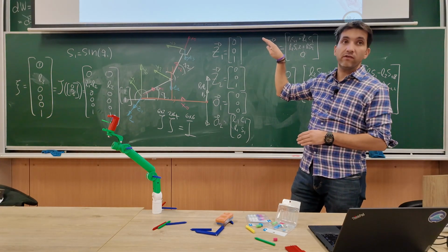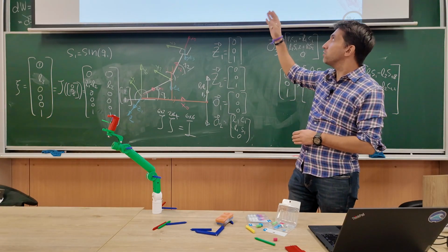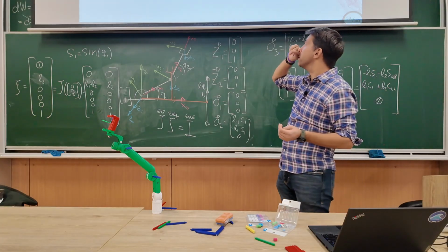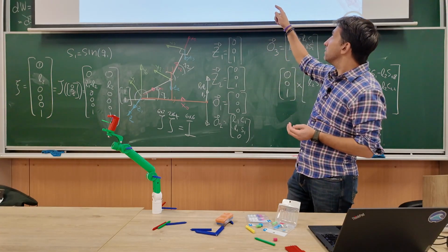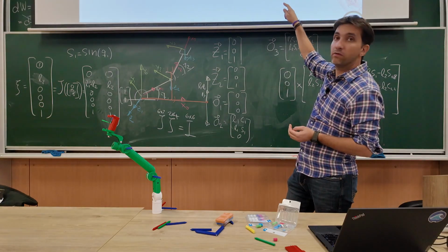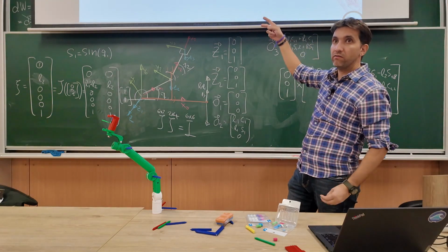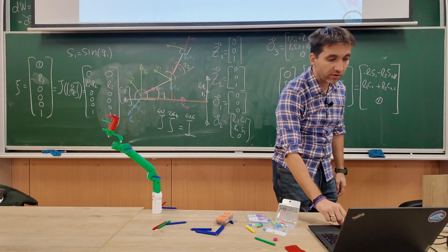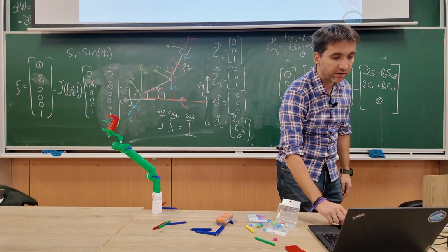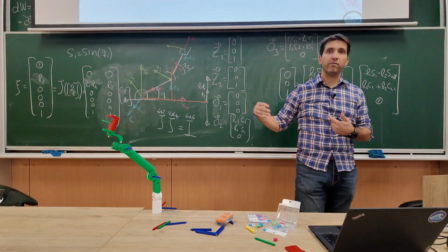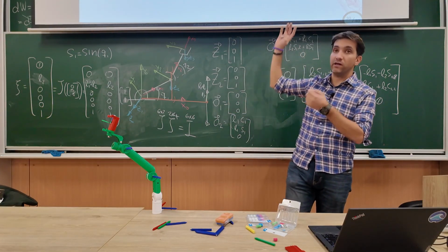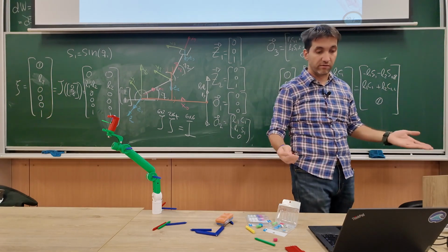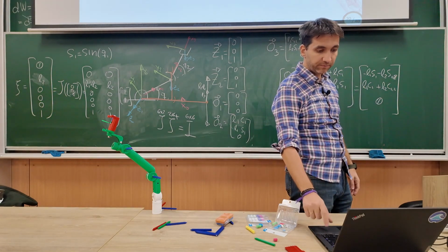What if I just ignore that velocity and I calculate the velocities just on z and y? Right? I can do that if I want. Then I end up with a 2 by 2 Jacobian, and I can do the inverse. But this will ensure I will have the desired velocity on the two directions I have here, and we don't know what will happen on the x, on the other direction that we erased, right? It might be whatever, because we're actually not controlling it.